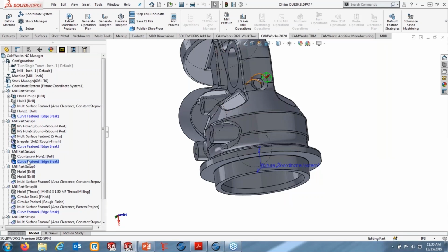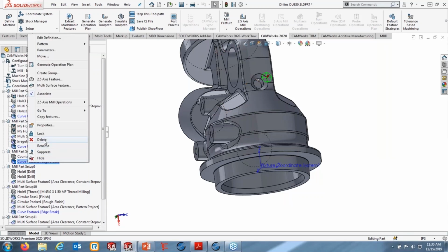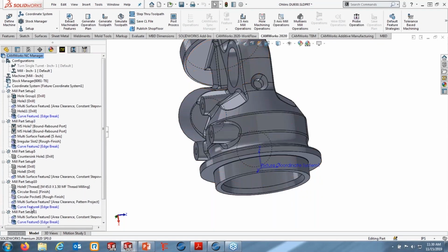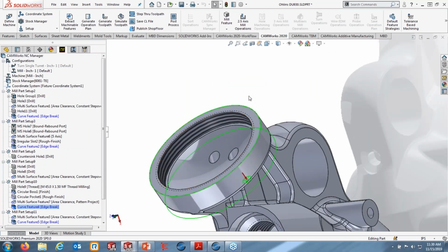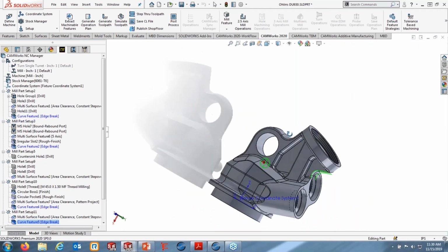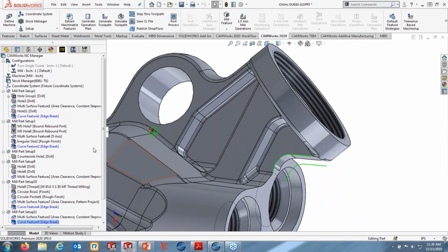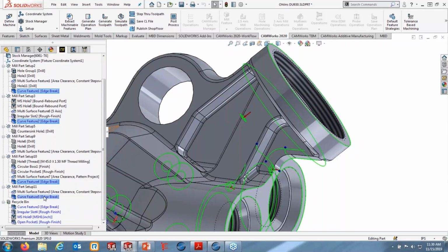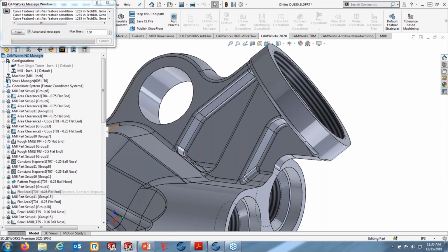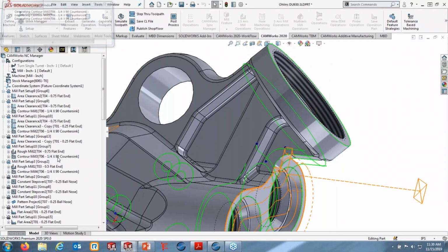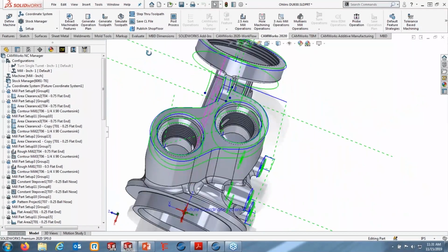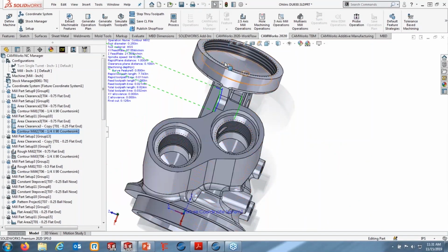Now this one is one example that I probably wouldn't want to deburr, so I'm just going to delete it. Don't like it, simply get rid of it. But things like the bore up here, or sorry, the outside diameter of this boss right here, another great one. And this over here on the opposite side as well. So it just means that I can quickly come through here and go, okay, generate those operations. And I'd do some reordering of this to put them in the right order. But it means I can come through here and generate toolpath to go and deburr some of this stuff.